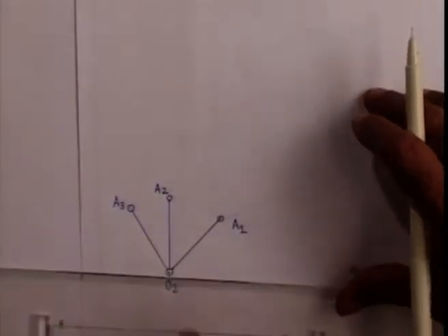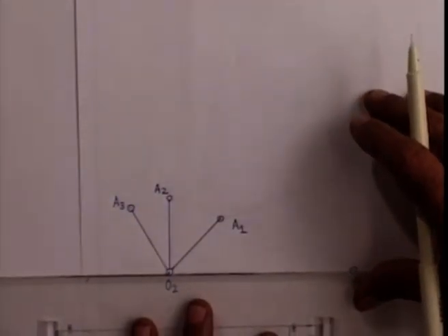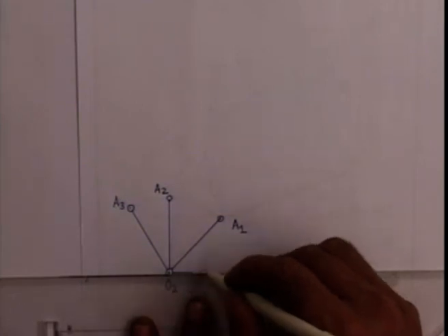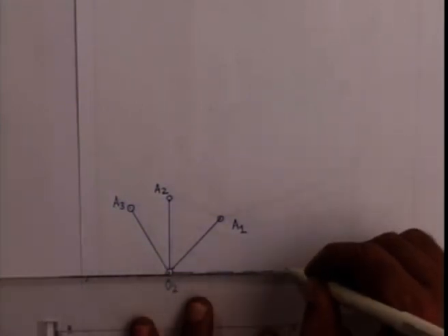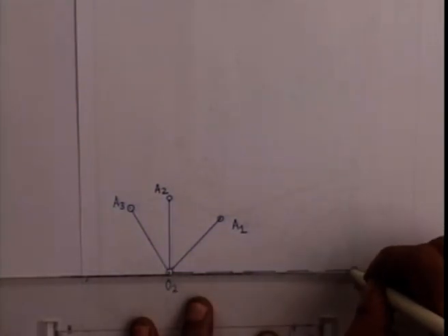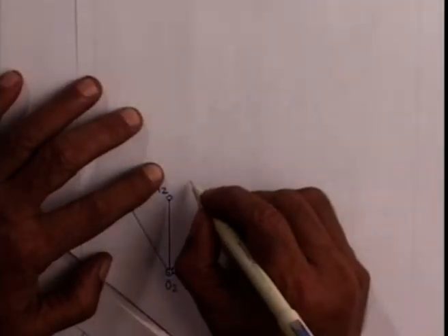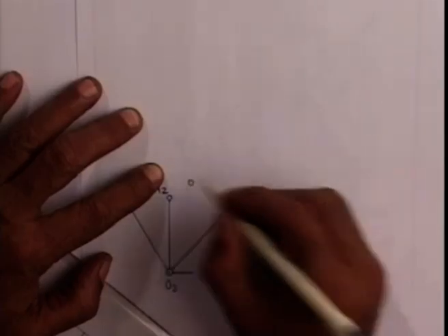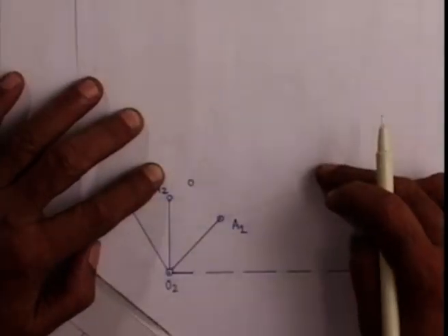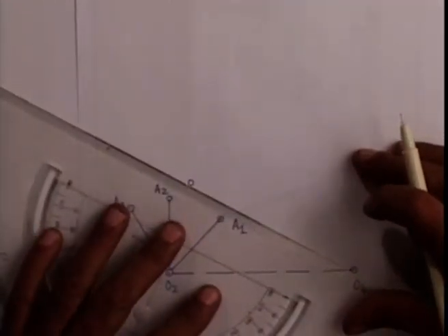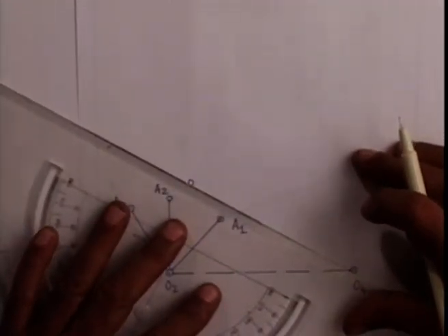Accordingly, to maintain the principle of kinematic inversion, that is to maintain the same relative motion, the fixed link O2O4 must rotate by an angle minus theta 412. O4B has been held fixed, so O4O2 moves in the direction opposite to theta 412, which was counterclockwise.